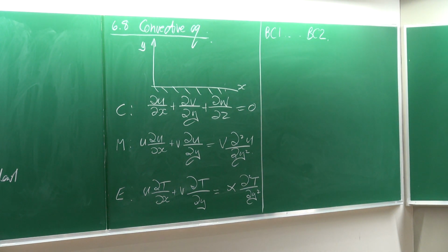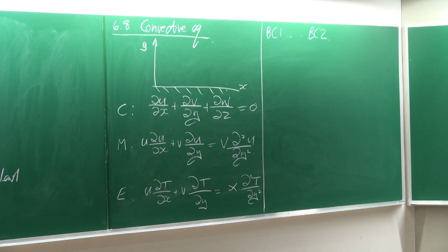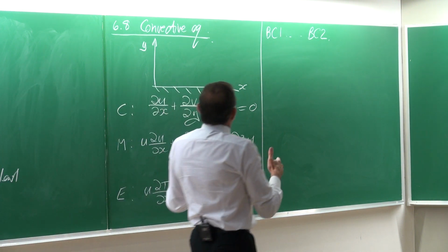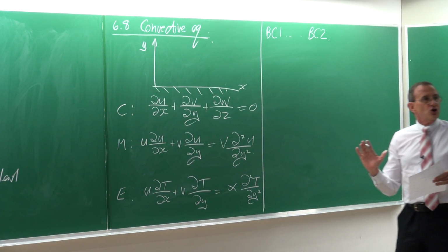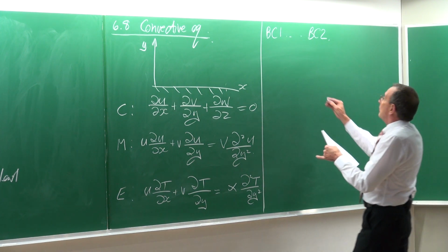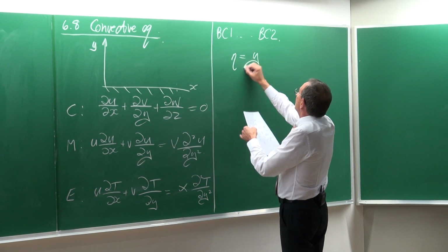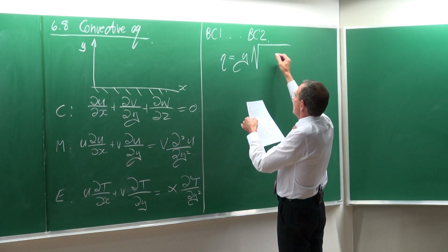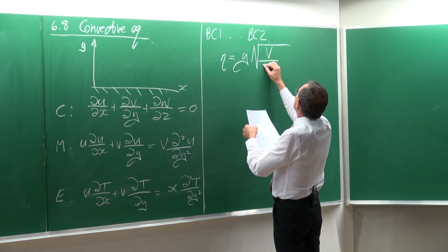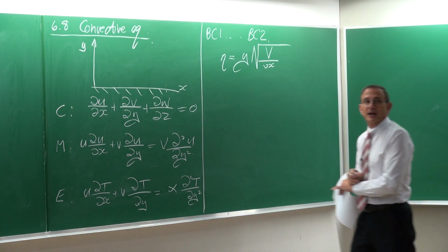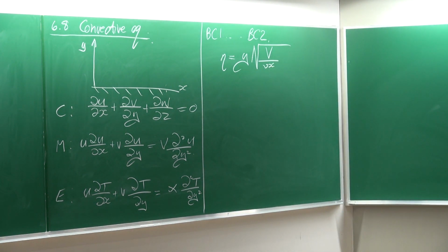And then with the thermal boundary layer, Ts here on the surface, and T infinity, and he uses all those boundary conditions. And then in 1908, he already came up with a sort of an analytical solution for this problem by defining a so-called similarity variable as y multiplied by the square root of u infinity divided by the kinematic viscosity times x.